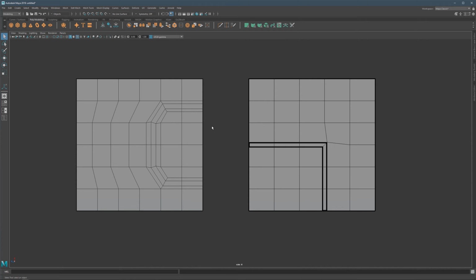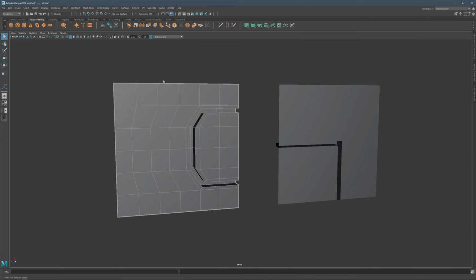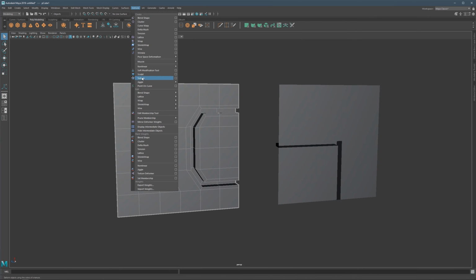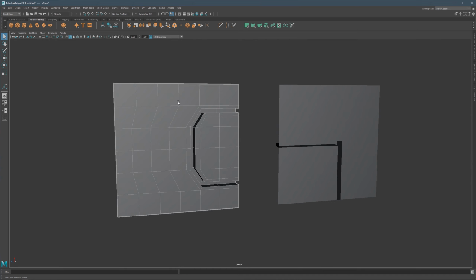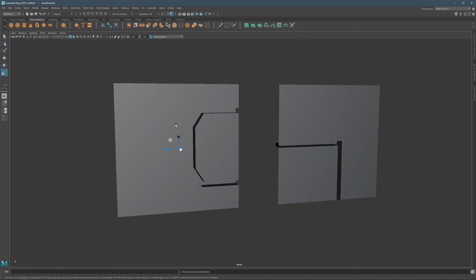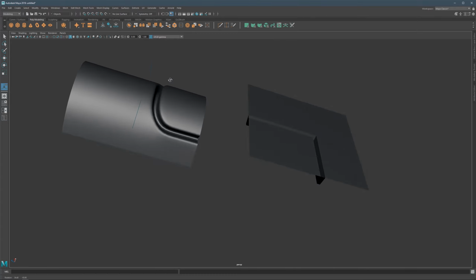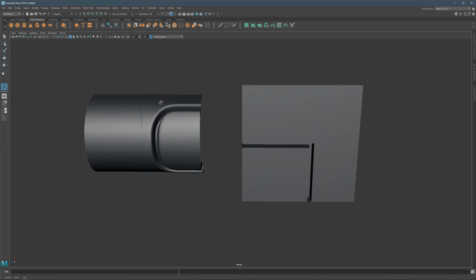It's going to look great on curved surfaces. So even now, if I want to use the bend deformer here, let's use nonlinear, let's use bend. And if we check how it looks subdivided, it is still going to look good on a curved surface.